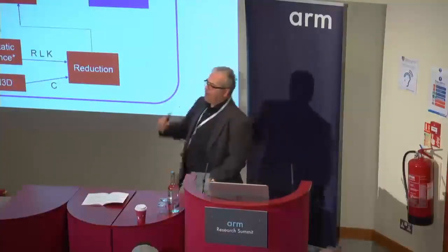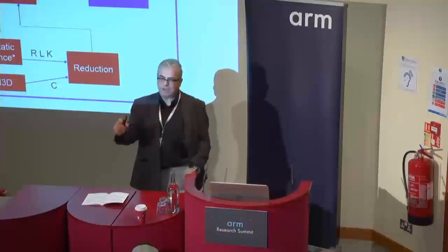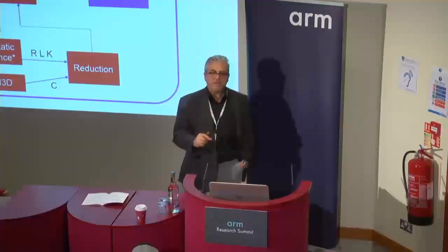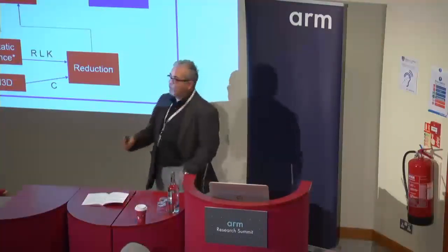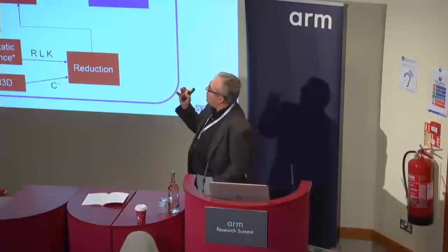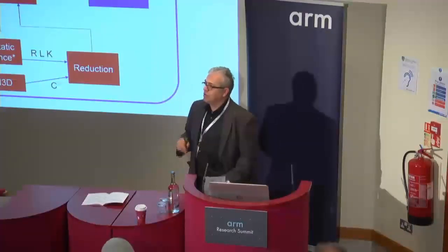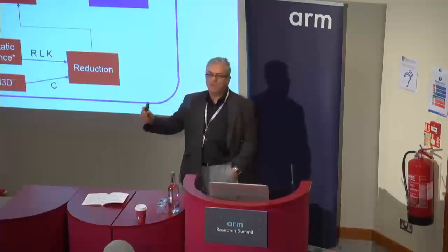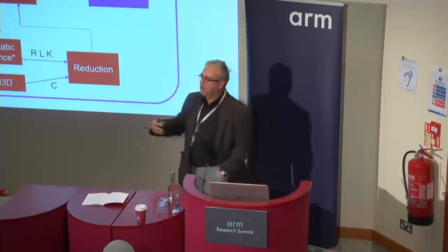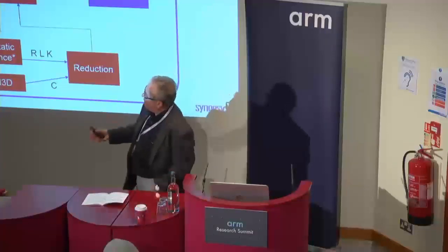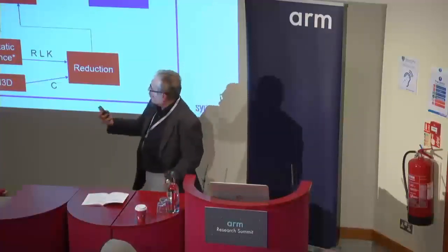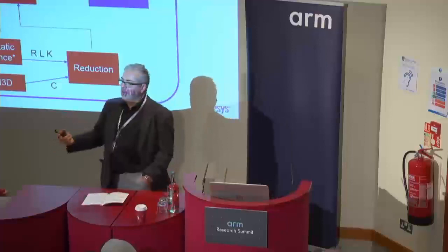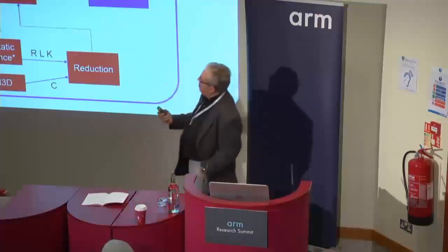So first of all, at the level of a device or a very small structure, you need very high accuracy. And that's where you need to have field solvers that will extract things pretty accurately. You cannot use field solvers beyond few devices, beyond a very small region. You need to have lookup tables when you go to extraction at a block level or a chip level, both for capacity, for speed, and you still need to maintain accuracy.